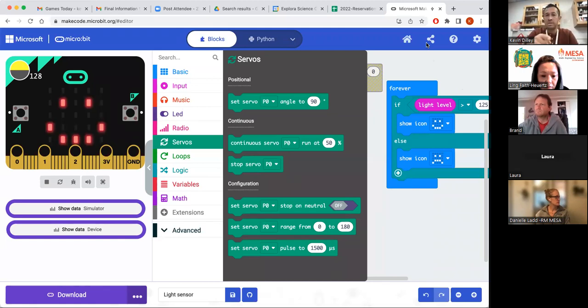And then a continuous servo is one that will just spin. You can't tell it a specific angle to go to. Usually you tell it how fast you want it to spin, and how long you want it to spin for. So if you have a robot, a little rover thing, you might have a continuous motor connected to the wheels, and then to make it go a specific distance you tell it to spin for 2 seconds, and it spins for 2 seconds and then stops, and you'll have to figure out how far that is. Okay, so that's what a continuous one is.